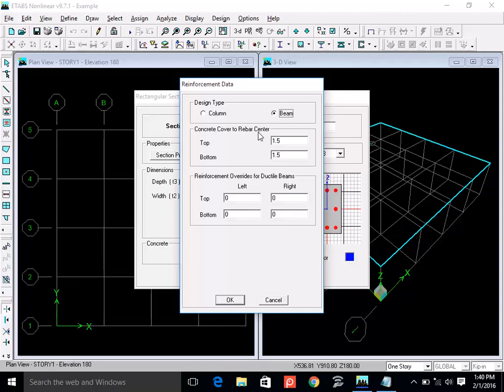Okay, look at this. You have the concrete surface, the soffit of the beam, and then you have the shear reinforcement, and then you have the longitudinal steel bar. What this is talking about is, from the center of the rebar, this distance, which is equal to what? It is equal to clear cover